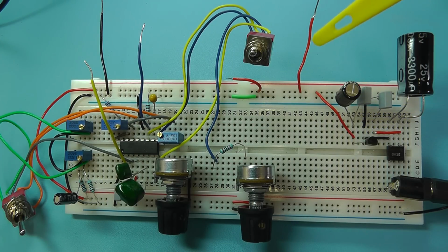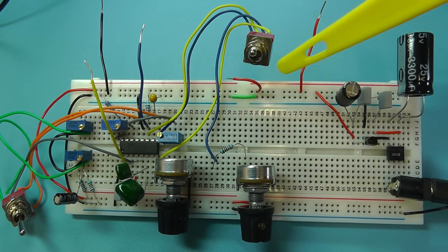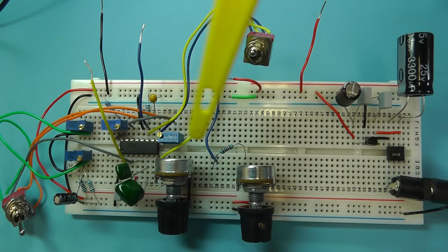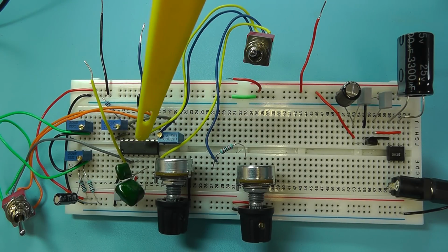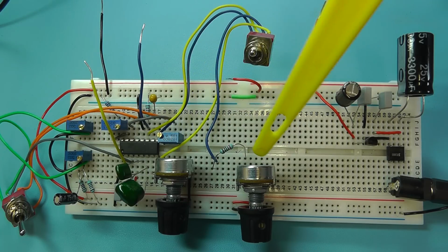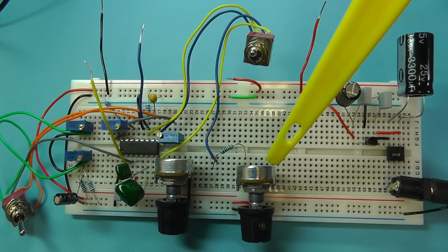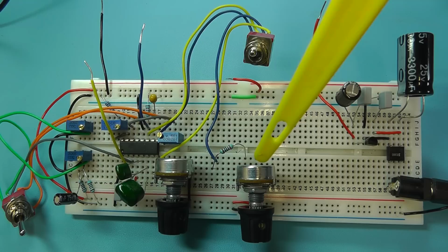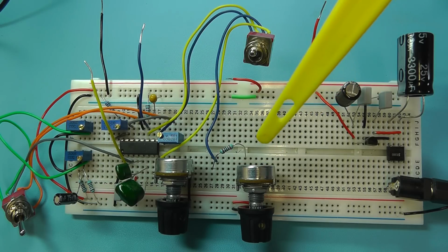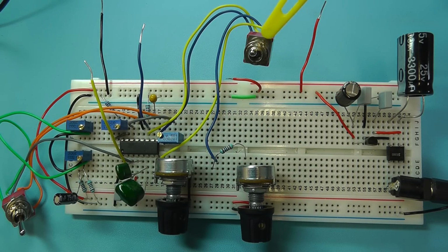So here we'll be getting 12 volts DC coming out, which I'll test before connecting it through to the rest of the circuit. On the remainder of the breadboard we have the main function generator IC, the XR2206. There you have the 200k linear pots, which we'll be using. That one there is the normal frequency control, and this one here we'll be using to alter the pulse width. The switch you see here is the one we'll use to switch the function of the generator from normal square wave to pulse mode.